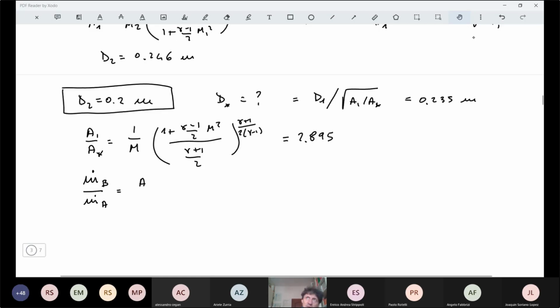So at Mach equal to 1, we will have the same condition at the throat. So the mass flow rate will be only related to the throat area. So we have here this throat area, let's say that we have calculated here with this diameter, is our throat area A.